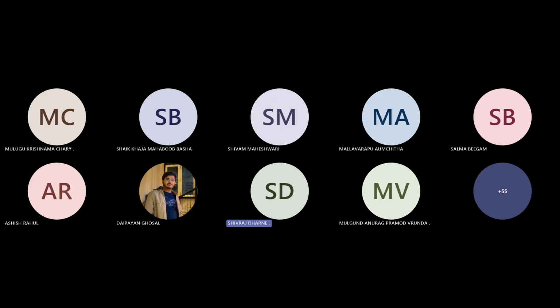You should have an electrical diagram, you should have a rack layout diagram, you should have a cooling airflow layout, power, how do you distribute, what are the redundancy blocks, right? Risk assessment, all that you have to put. Then you can tell the whole summary. You can make a very nice PPT and provide a simple executive summary of what you did, right? And you can say how you built the whole system.